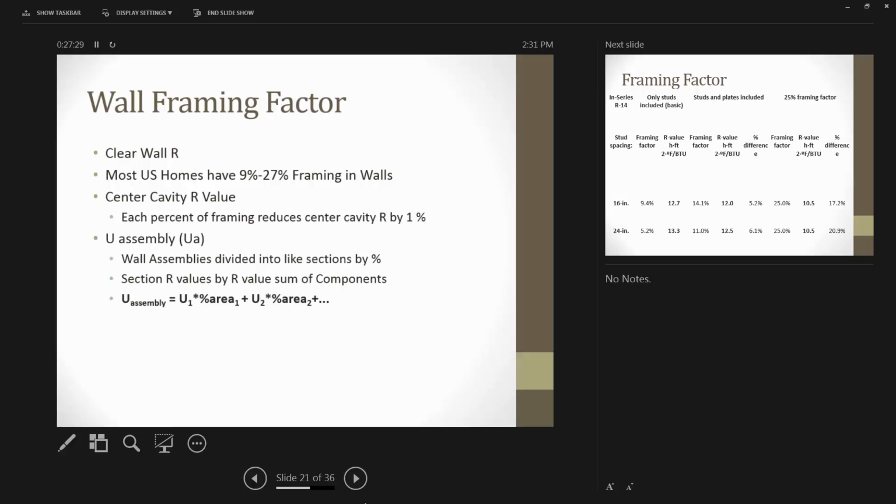So if you think back to that wall example that we had that was just a square wall, and that was 96 square feet, and that wall was an R13.4, if we've got a big picture window in there, that's 10% of that wall, and that window is going to be a 0.30 U value. We then have to add that percentage to the wall percentage.